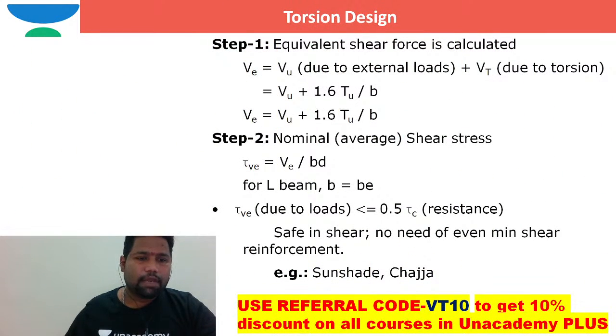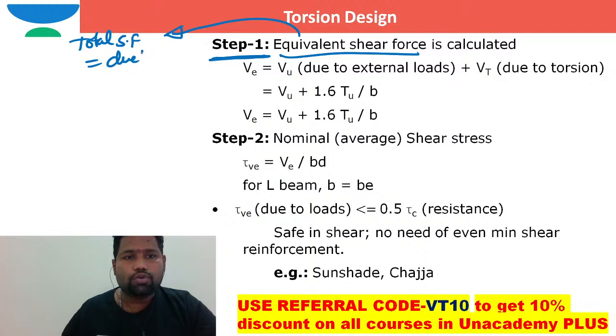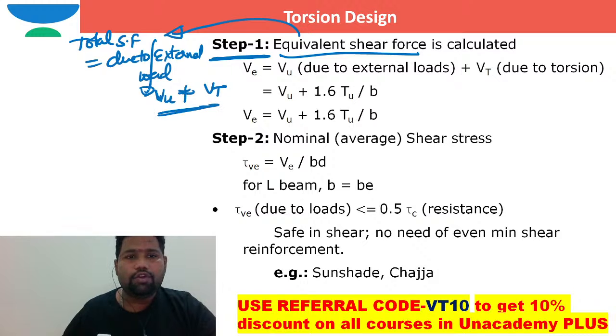So coming to step number one. In this step number one, I need to find out the equivalent shear force. The equivalent shear force is the total shear force which is due to external loads and due to torsion. Due to external loads, it is nothing but Vu. But shear force due to torsion is nothing but Vt. So Vu will be given to you.